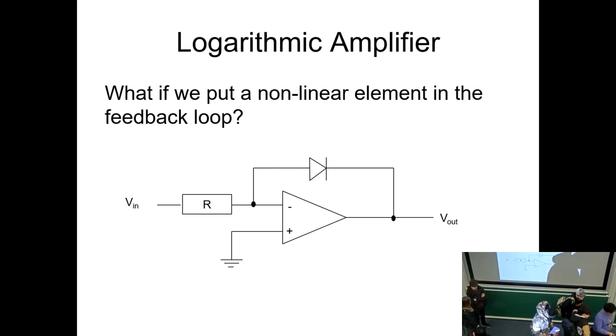And what is meant by transistor matching? Two transistors opposite each other have to be identical. Same size, same shape, everything else. If they're different at all, they're not matched. In a silicon chip, they can be made to be very, very accurate to each other. If you make this whole op-amp circuit on a circuit board with discrete transistors, they'll all be different, and so the performance will be very bad. You have to integrate them onto a chip and make them all identical.